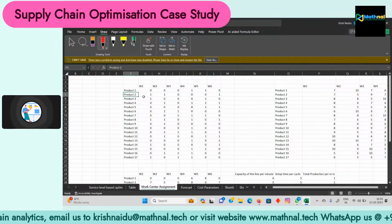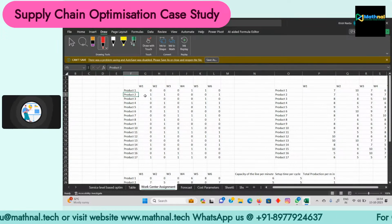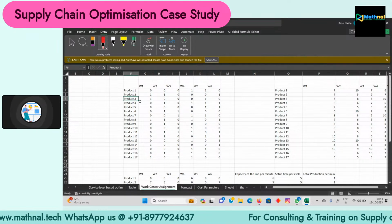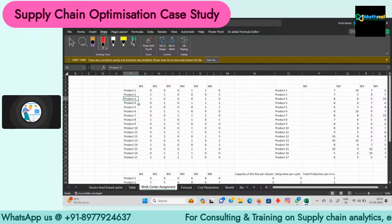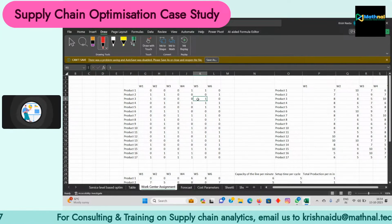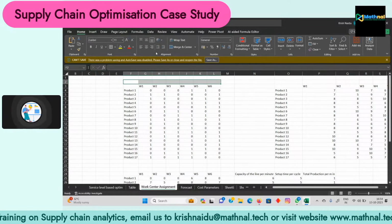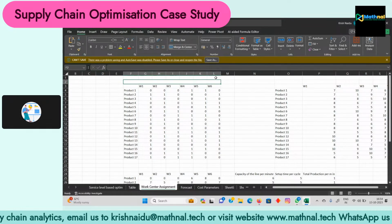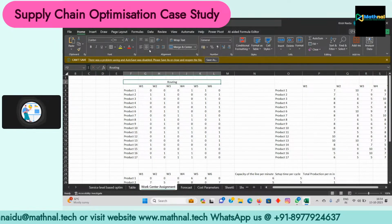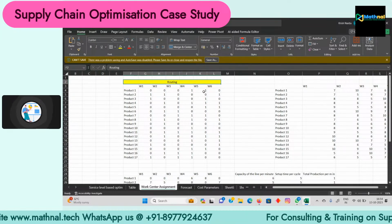Similarly, for product number two, if I have to manufacture it, I have to pass the raw material through work centers one, two, and six. If I have to manufacture product three, I have to pass the raw material first into work center one and then after that work center five. Okay, so this is my route. This is called routing of the products. So this is how the products will be selected for manufacturing through work centers. This is the routing.